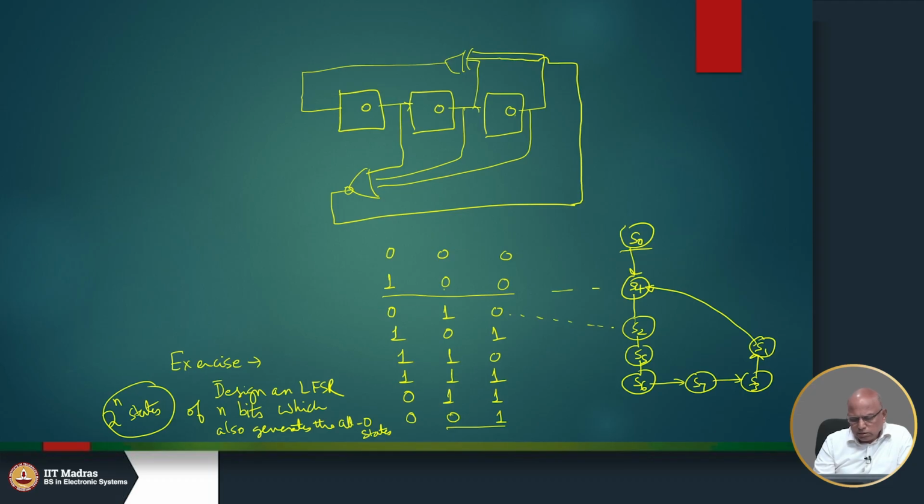See, in our BILBO register solution, unfortunately we have to first load the BILBO with a seed. Only then we can start operating the BILBO as a PRPG. But if you could simply reset the BILBO and put all 0 as the initial seed, it makes life a little bit easier.